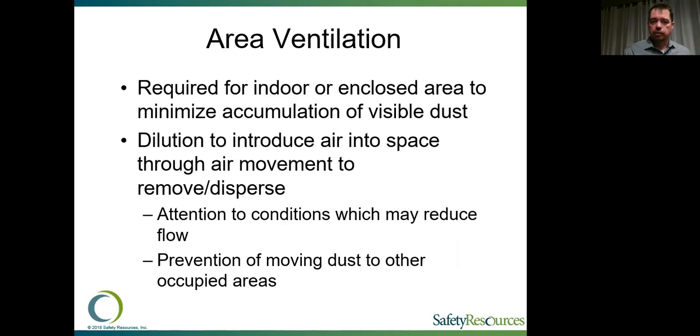So it's definitely going to be required for any indoor and enclosed area, and that's going to help minimize the accumulation of that visible dust. So ventilation is going to provide some good dilution. You're moving fresh air into a space, and you're breaking up that immediate concentration that the employees may have exposure to.